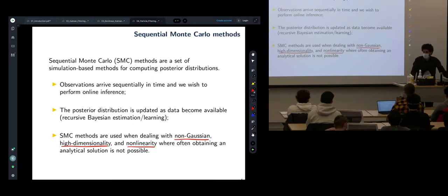But the poor robot has no idea you did that. So it's trying to track. The robot thinks it's here. You move the robot to the other side of the room. It might never happen, or it might take a very long time for the robot to recover from a sequence of observations what just happened. That's the kidnapped robot problem. So particle filters, because they can track multiple hypotheses, it's more likely a particle filter can recognize that and basically shift the mass of the estimate to a more likely hypothesis, which might be the other side of the room. Okay?